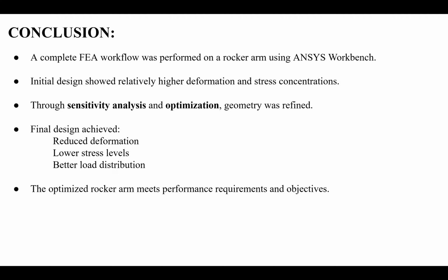And through systematic sensitivity analysis, we identified fillet radius and arm gap width as key variables, and then we arrived at the best performing optimal values. So it reduced the deformation to 0.29 mm and the stress to 135 megapascal, achieving better load distribution. And overall, this work highlights the importance of combining FEA with optimization techniques to achieve stronger, safer, and more efficient mechanical design. Thank you.